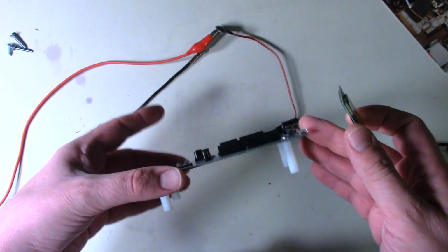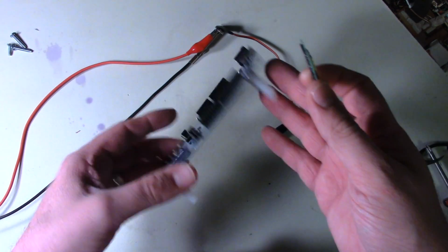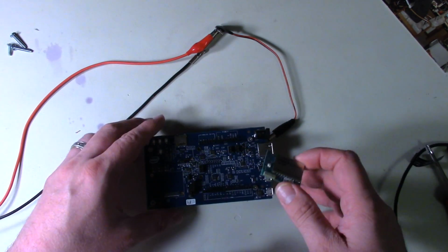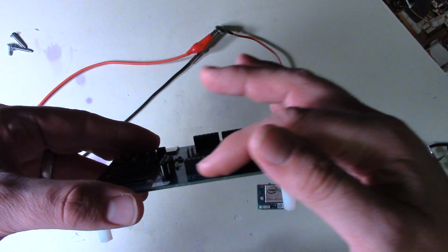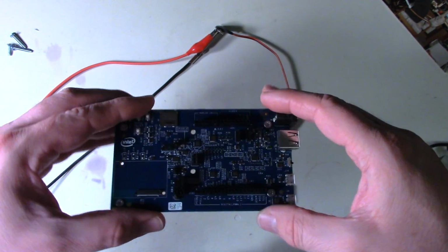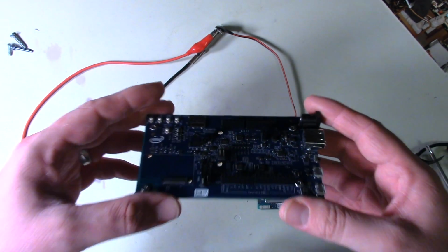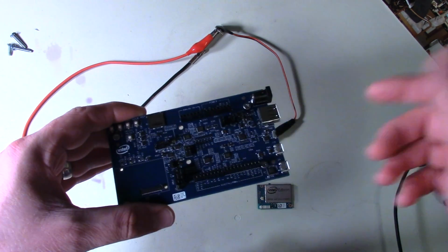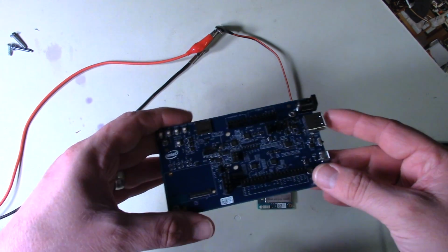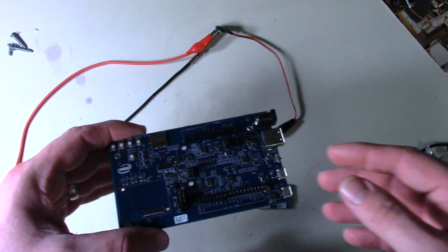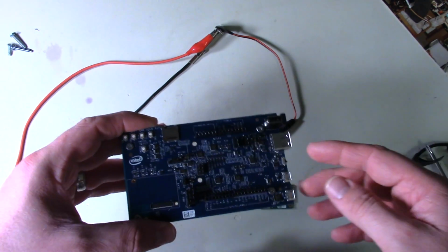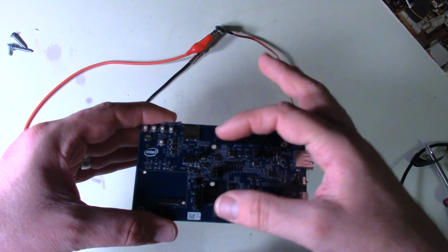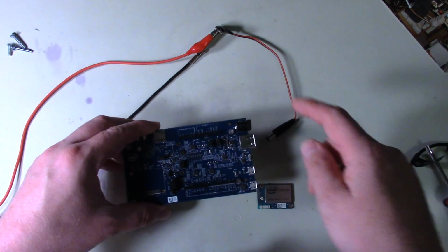However, in this little setup rig that they give you, they even give you these nice little plastic standoffs. This little setup rig, you can give it 5 volts and it won't be a problem, because as you can see, it has the Arduino-like shield connectors, because you can actually program this with the Arduino IDE. As you saw in the previous scene where I was at the PC, there was that Arduino IDE. It's a kind of mod for the Arduino IDE, so you need to download the one from Intel to be able to use your Arduino sketches and your Arduino shields with this. But you get the 5 volts.